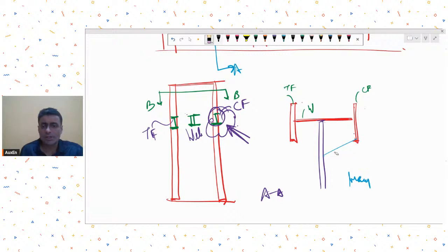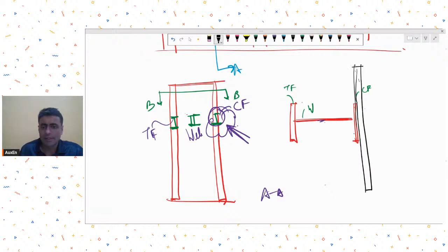Sometimes in cases of girts, what we do is that girts are usually on the outer face. So a girt is like this. As long as the compression flange and girts are connected together, it's fine. But let's say the compression flange was on the reverse side. Reverse side means the opposite side to which the girt was connected. Now, in such a case, again, we may provide some element like this, which is called the flange bracing.